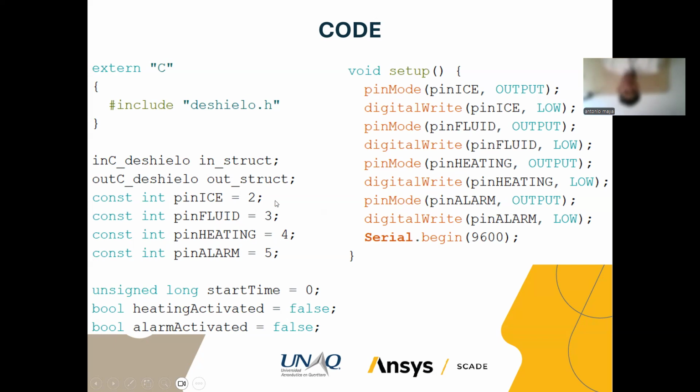I didn't know we can't use pins 0 and 1. They have a restriction for use in this kind of implementation from another software, because they're going to take values for TX and RX. So they're receiving and transmitting. So we cannot use them. And it took me like maybe 2 hours to figure it out. So we're using pins 2, 3, 4, and 5 for the pins to connect the LEDs.